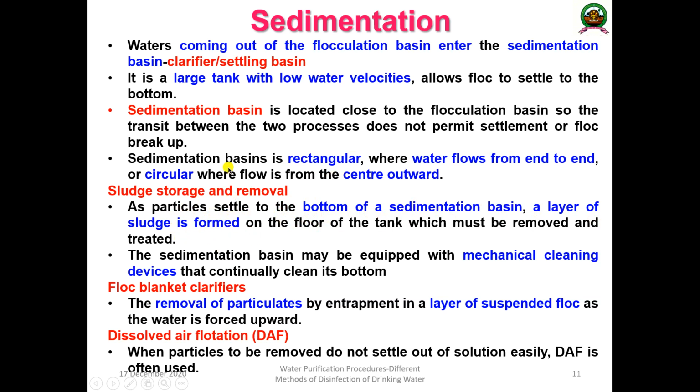The sedimentation: the formed flocs material that is settled at the bottom combines with all the particulate matter to form something called a sludge, which is formed on the floor of the tank and must be removed and treated. This sedimentation basin may be equipped with mechanical cleaning devices that can be used to clean the bottom of the tanks and remove the flocs.